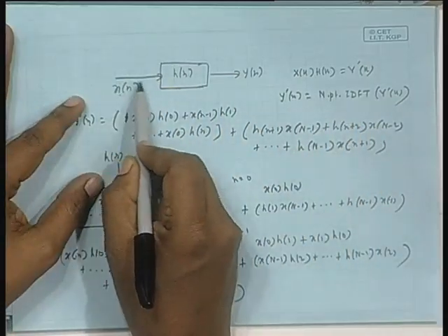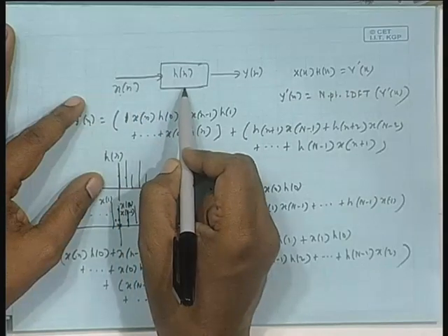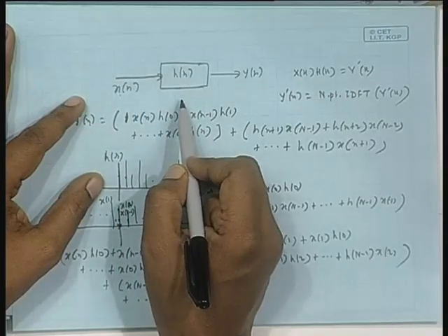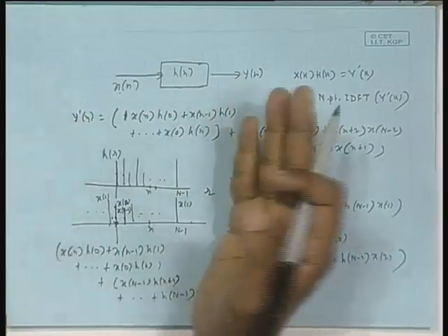So, I am to make these and y[n] the same length. That means, this was length capital N, so I add M minus 1 zeros here. This was length capital M, so I add N minus 1 zeros here. Now, if I convolve them, I still get the same sequence, because zeros do not change any result.